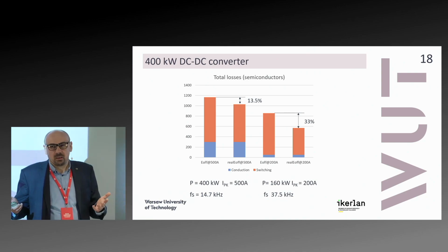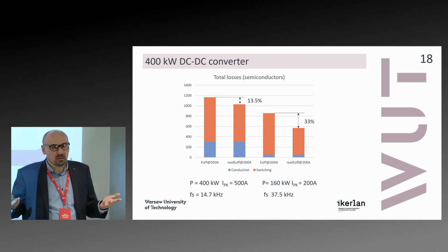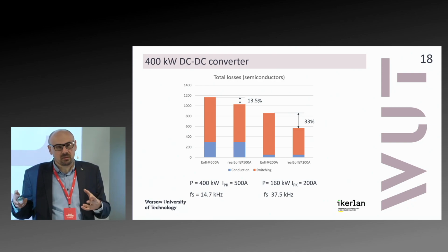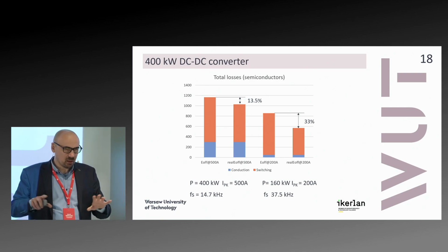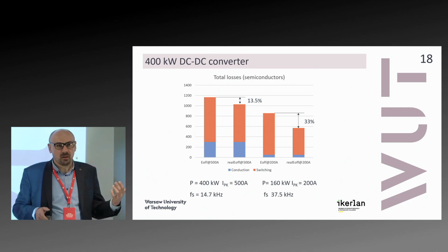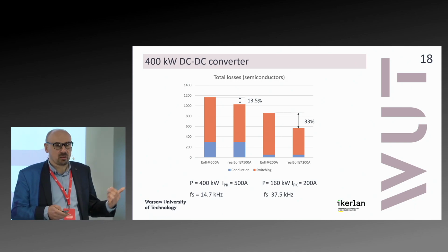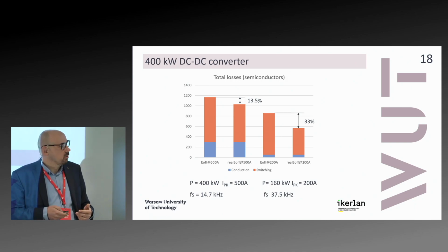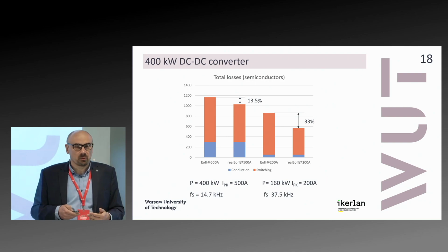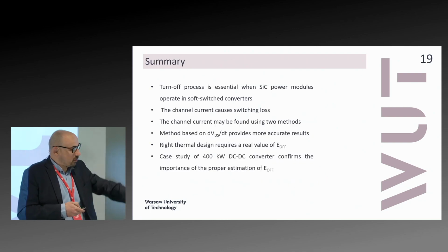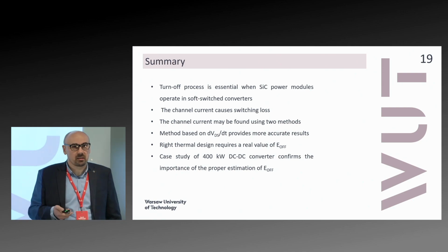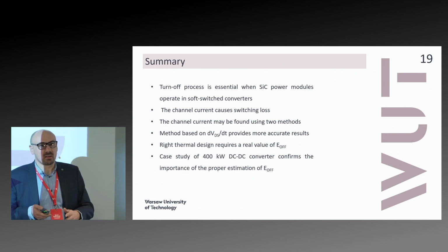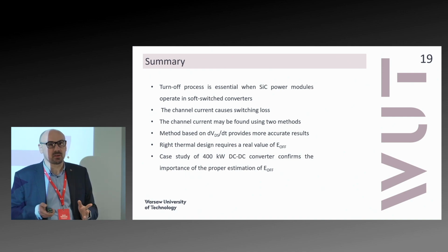So now, designing the heatsink, doing this electrothermal design, I think that at least for these high power modules, we need to take into account this issue. So to summarize my talk, as I said, this turn-off process is essential for soft switch converters.